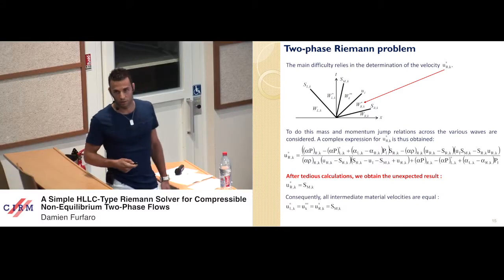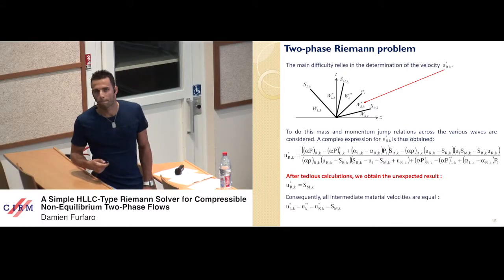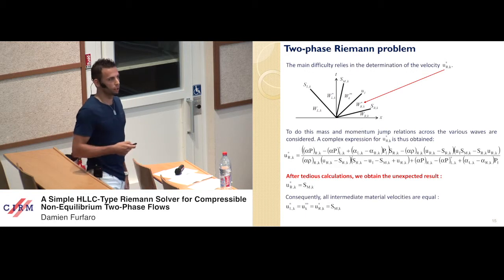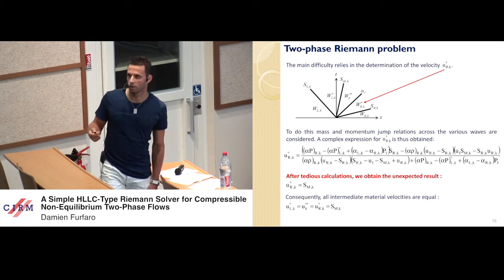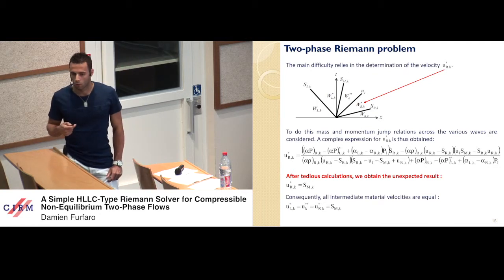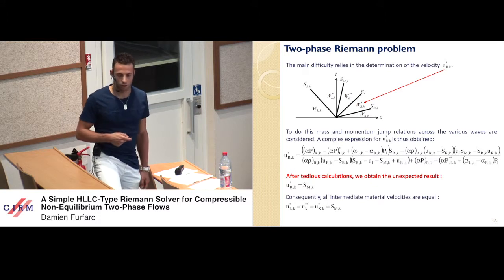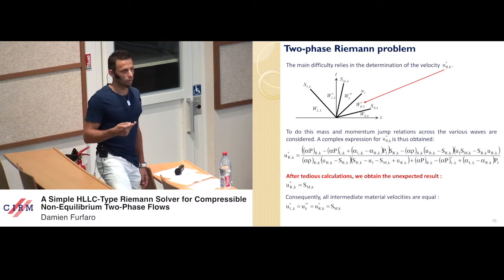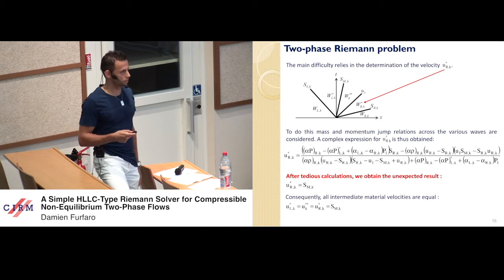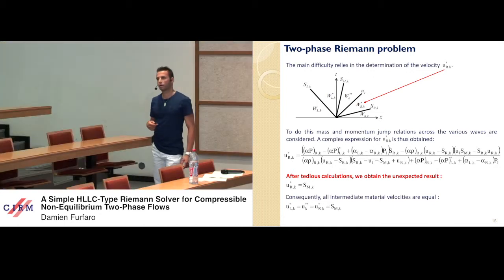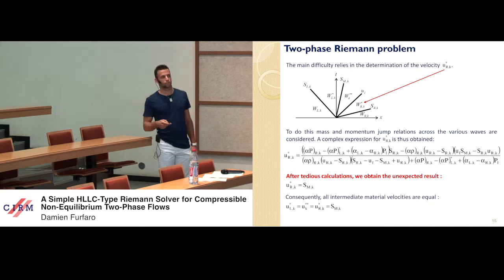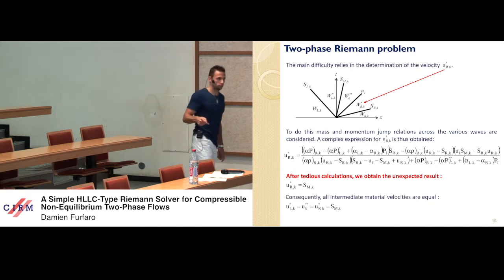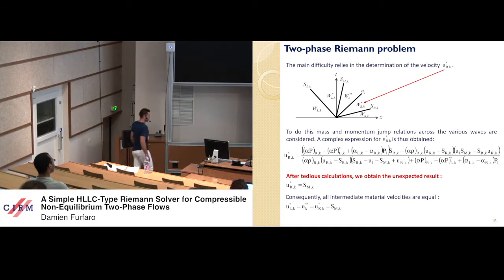This unexpected result can be explained if we consider the calculation of SMK. SMK was calculated with the HLL approximation, but its calculation takes into account the contact with the other phase through non-conservative terms. So we obtain this result, which simplifies all the calculations.